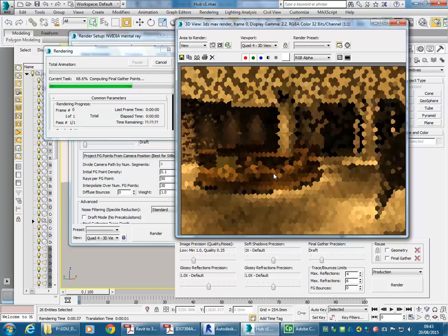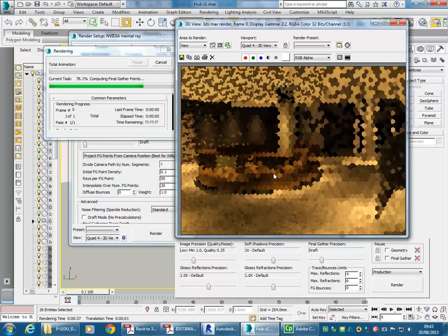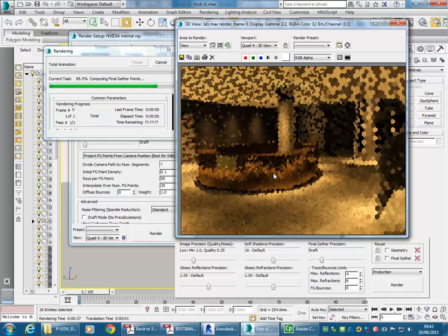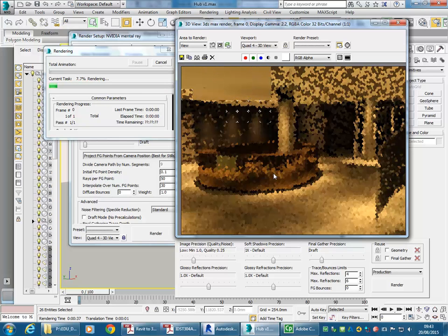In Revit, downlights by default are set to be incandescent lights, and you can easily change those to a different kind of light, or just change the temperature to a cooler temperature to make it less warm. You can also adjust it with exposure, but I'm going to try and get you to do it with the lighting temperature. It usually looks better, but you definitely want to be aware of the options you have to control it with exposure.